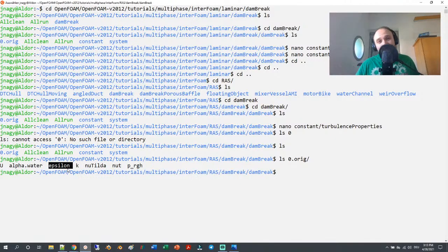It is possible that this model is unstable. For that problem, I don't know, because I rarely use the k-omega model. I either use k-epsilon or k-omega SST. So maybe you might be luckier with the k-omega SST model if you are allowed to use that.